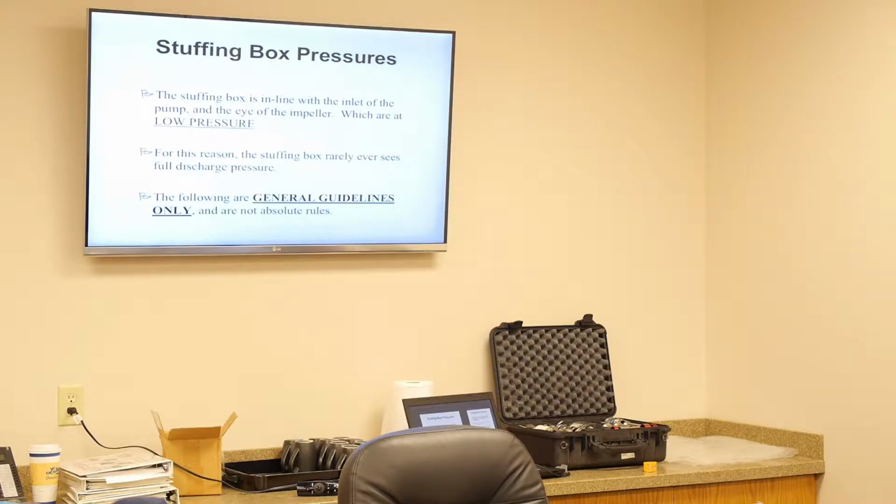The reason it's at lower pressure is as the velocity changes, your pressure gets higher towards the outside. Everybody with me so far? So from that standpoint, your pressure is always going to be lower at the stuffing box.